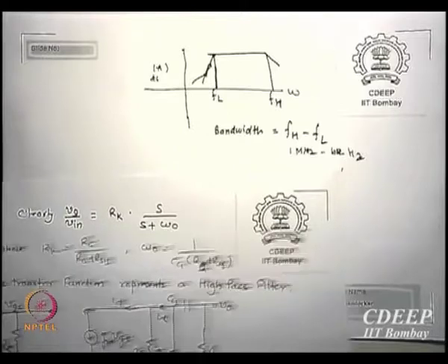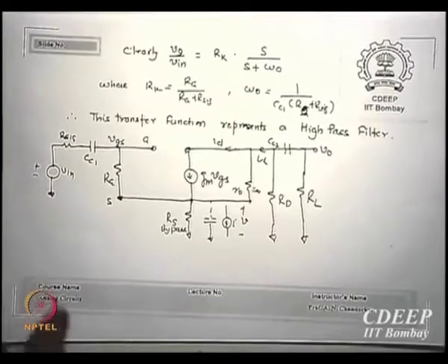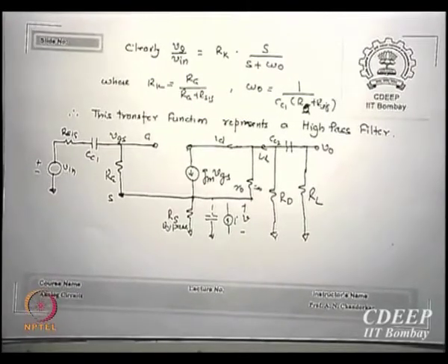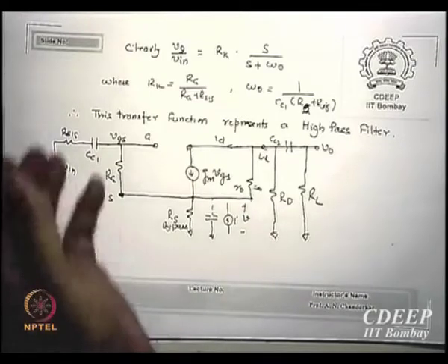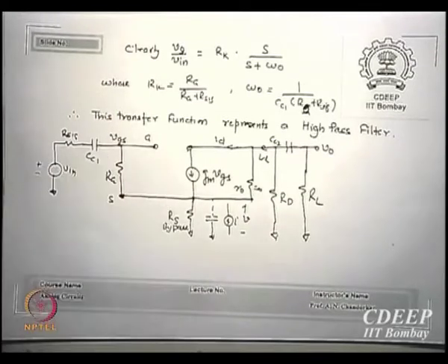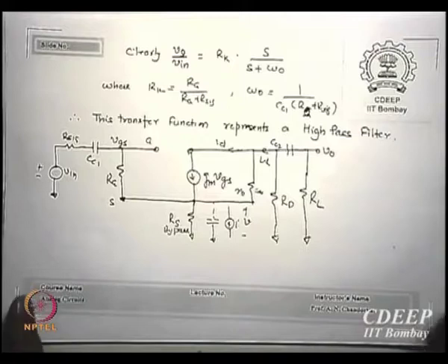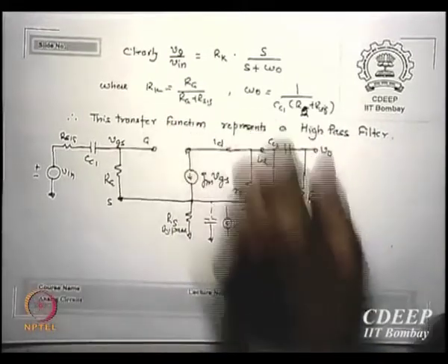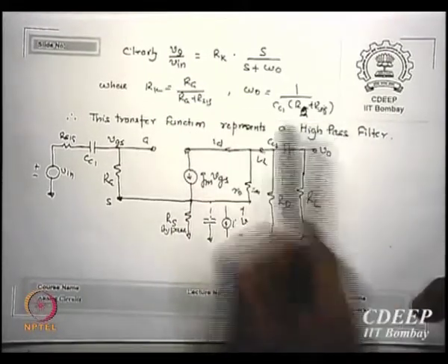So where are these low values coming from? CC1, CC2 and CS, these capacitances being very high, will start dominating at low frequency. Is that clear? So first thing, we want to now calculate the effect of CC1, CC2. For CC1 I have shown you the pole.